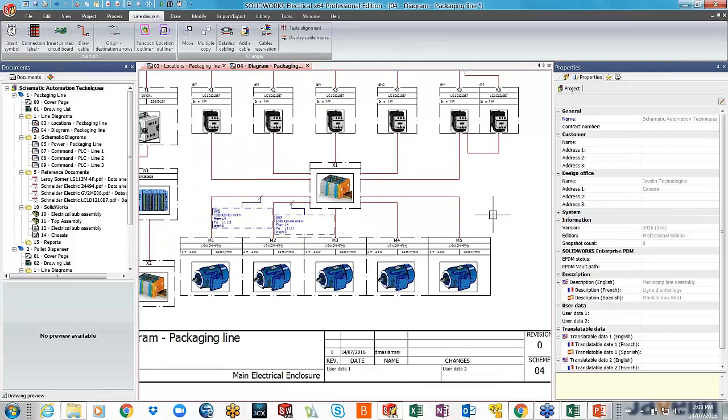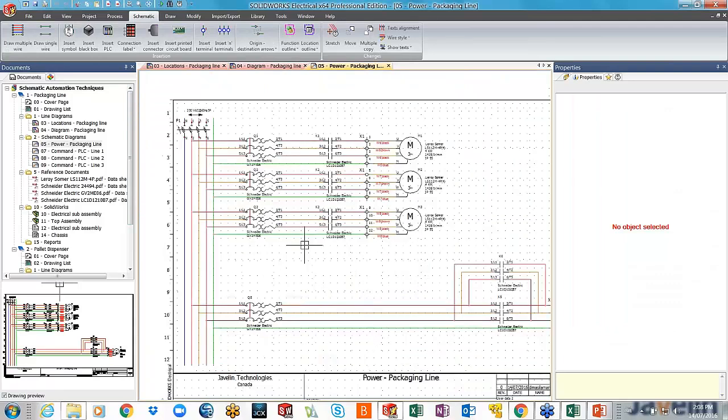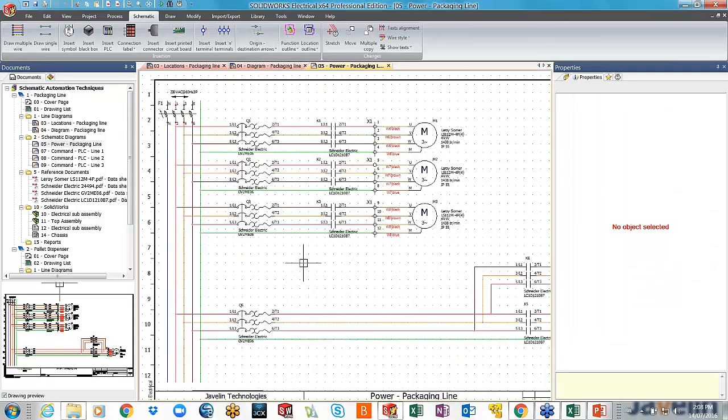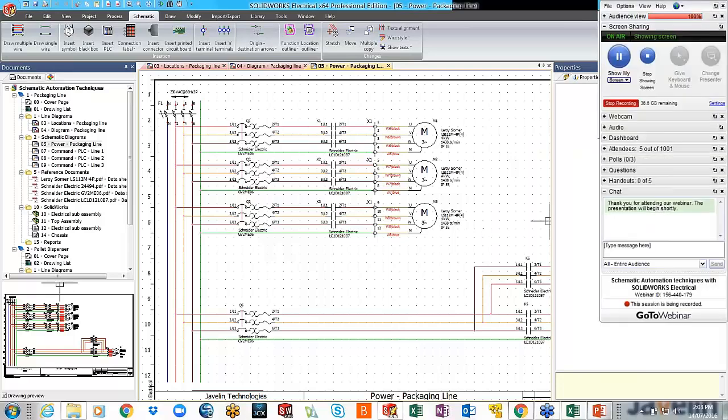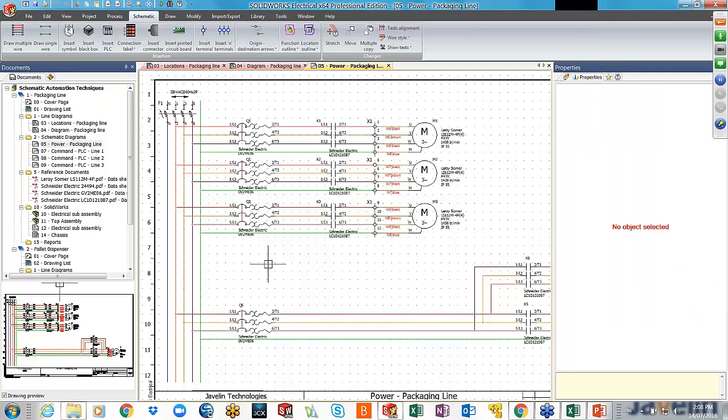So, like I said, there's going to be different levels of design experience as I go into this. The first one was me just dropping in our single line representation. I dropped in a symbol, I dropped in a cable, I gave the symbol some information. Let's step up, and we're going to now get into our multi-wire or schematic representation. In the schematic representation, we simply end up having to add some more information over here. So we've added a motor on one of the pages. Let's see how we can add that motor also in the schematic.